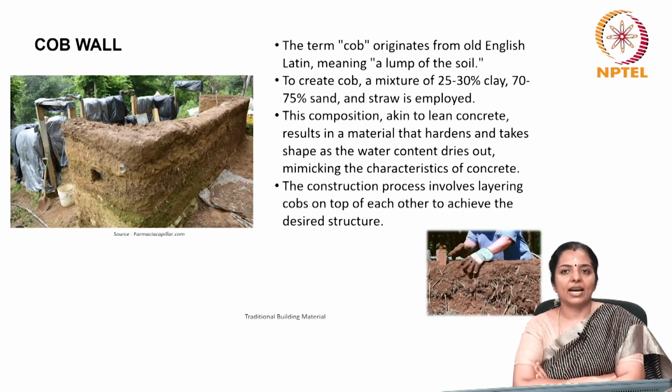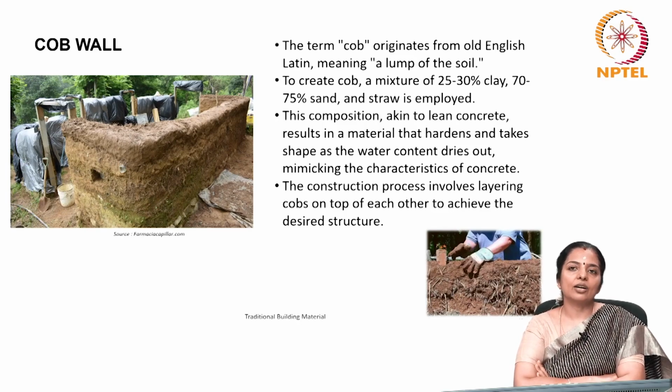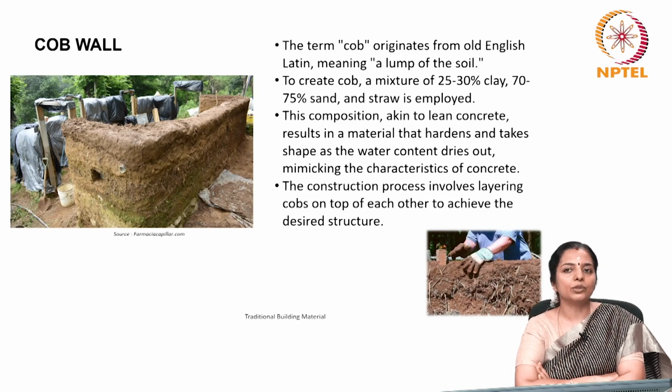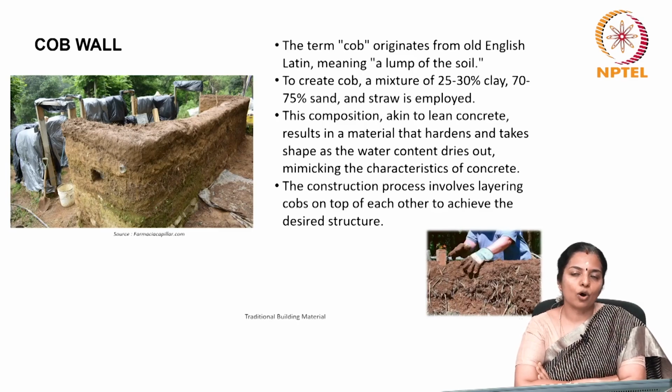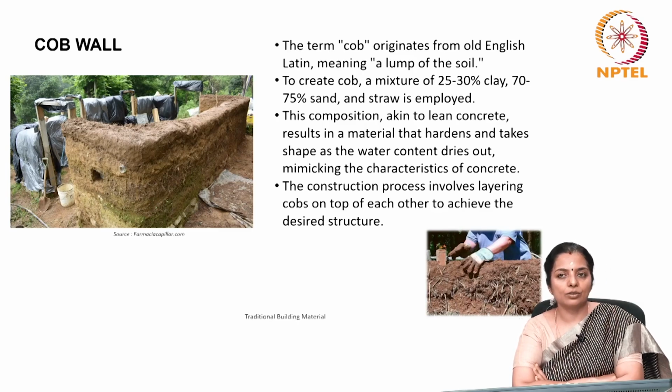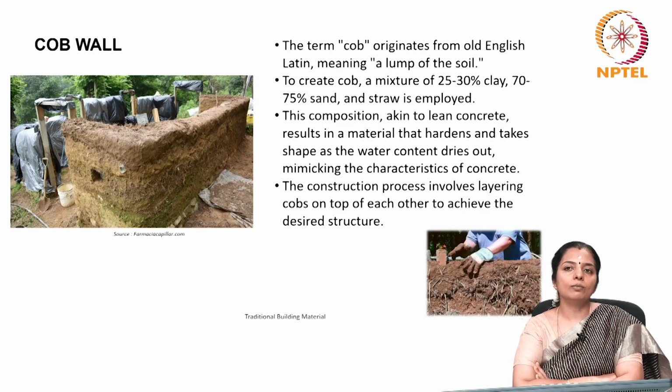So using the hands and the feet, the cob builders create lumps of earth which is combined with straw and sand. The cob is inexpensive to build, and it is simple to learn this technique also. The absence of any formwork or ramming or cement or rectilinear bricks or molds in cobs allows for creation of very organic shapes like curved